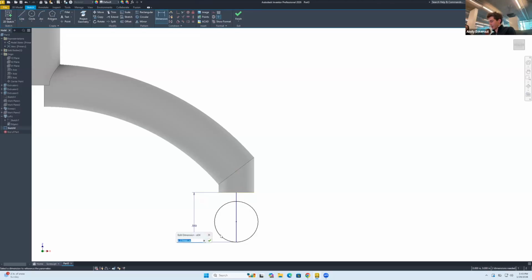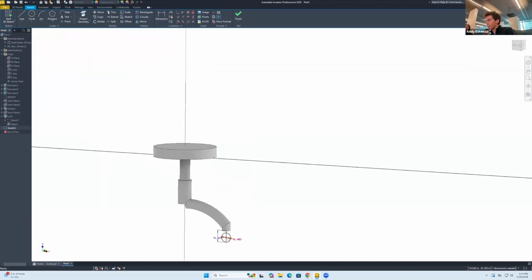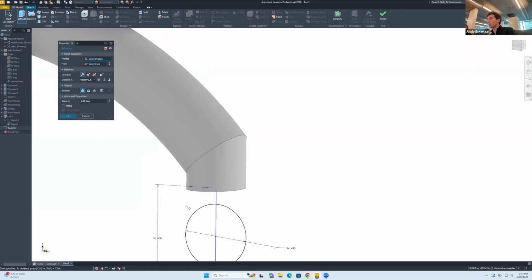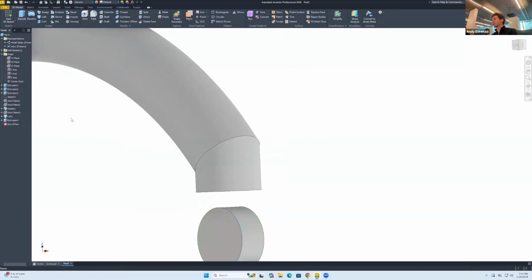Let's make that 0.15 times height. And let's make this 0.12 times height. Okay. And what I'll do is the following thing. I'm gonna go here to model, extrude. We're gonna make it symmetric, and we're gonna extrude by 0.2. Okay, I think that's decent. I'll go here to fine.